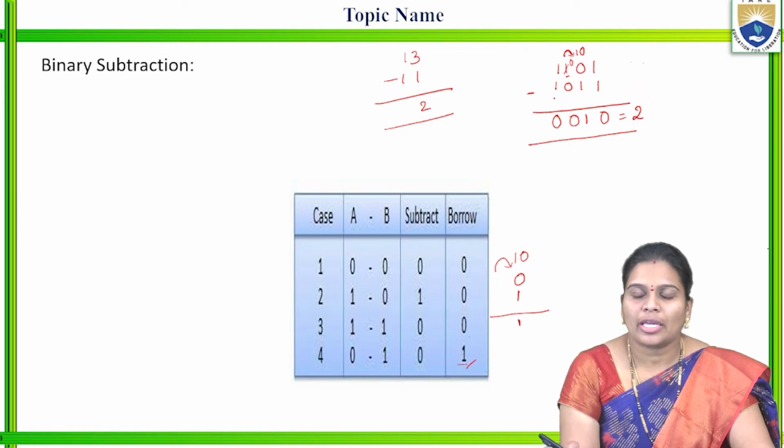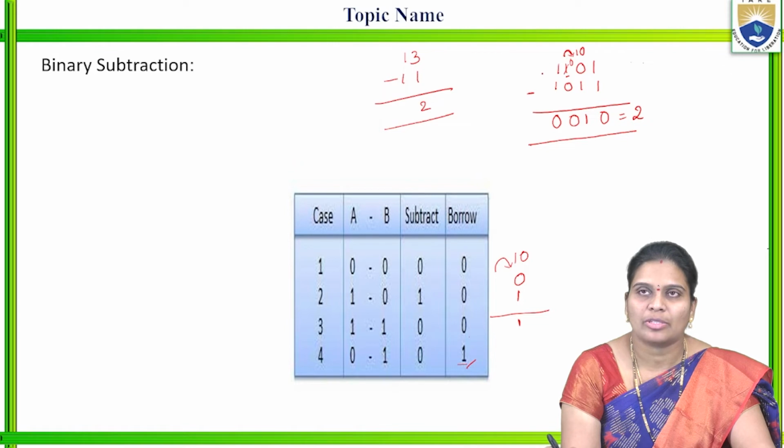Here we are taking a larger number of bits. In such a binary subtraction, we have to take borrows. Compared to decimal subtraction, binary subtraction is somewhat complex, because we take a borrow from previous bits, and again borrow from the bits before them. To overcome this, we go to complements: the r's complement and the r minus 1's complement.